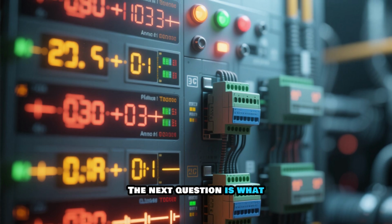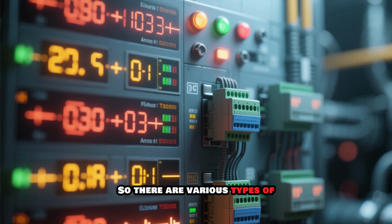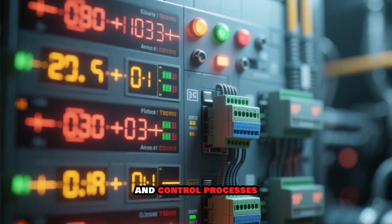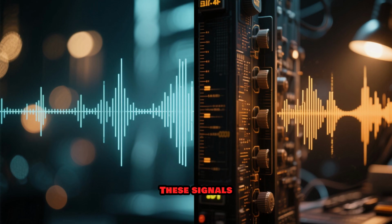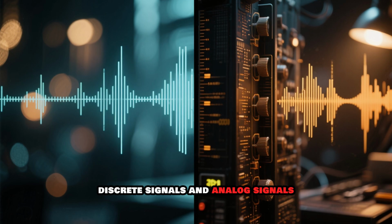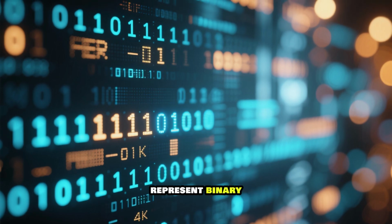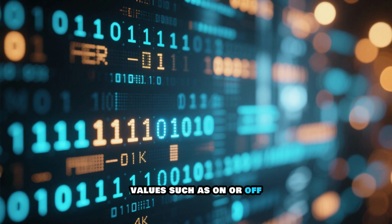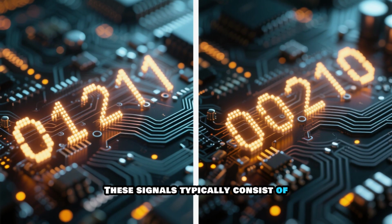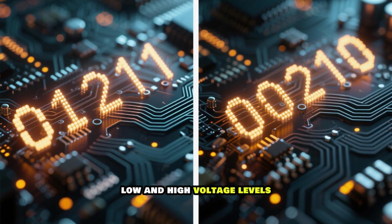The next question is, what are the different types of PLC signals? So there are various types of signals used with PLCs to communicate and control processes. These signals can be broadly categorized into two types: discrete signals and analog signals. Discrete signals are used to represent binary values such as on or off, true or false, high or low, etc. These signals typically consist of digital values like 0 and 1 or low and high voltage levels.